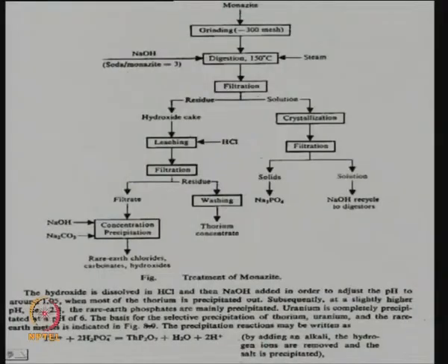What does not dissolve contains iron, titanium, etc. Here it is opposite. What does not dissolve forms a cake which has the metallic values, thorium and rare earths. It happens in the alkali leaching process, and may not happen in acid leaching. That is one advantage perhaps which has attracted people.